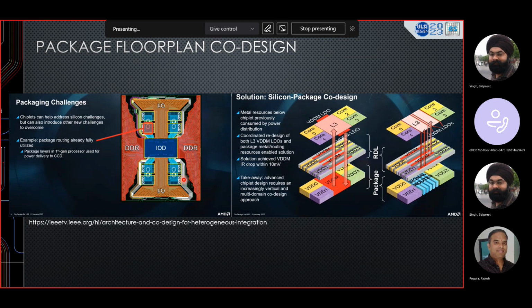And they were directly talking to the IO die. You have a path directly in the package routability from the CCD die to the IO die, right? The next generation, they had some more chiplets, right? They had 8 of them. Now, this particular CCD die, how can you talk to the IO die? They had to have the package routing traces coming through one more CCD die and talking to the IO die, right? Now, this was not done before.